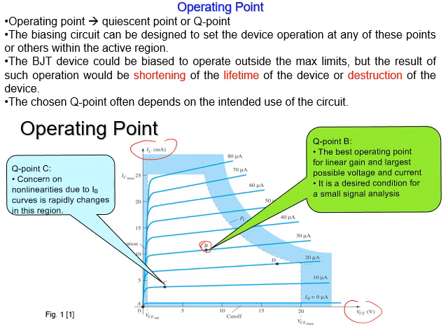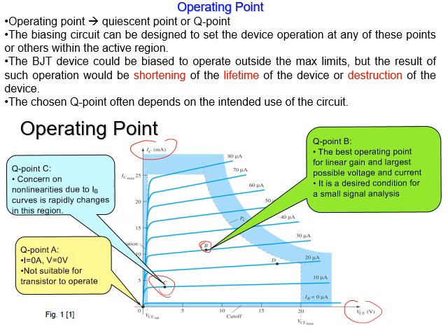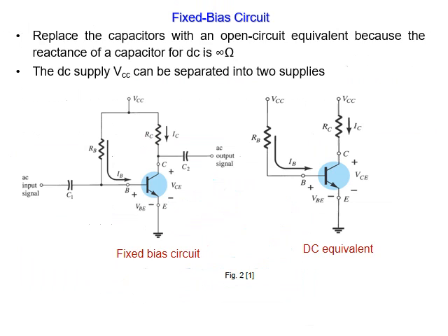Okay, the concern with having the Q point, the operation point for the transistor, at a low value here, as an example, is that nonlinearity occurs in the curve and in the operation of the transistor. Never work at the 0, 0 origin.